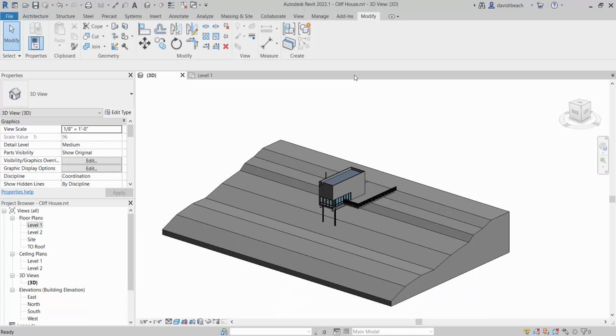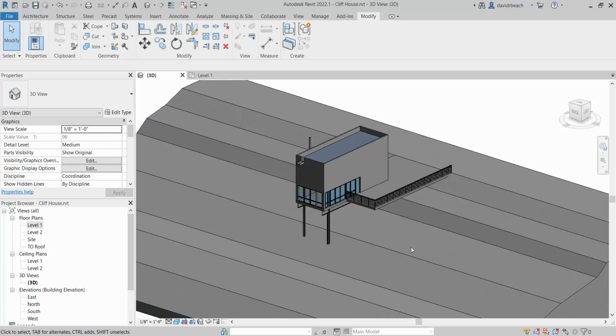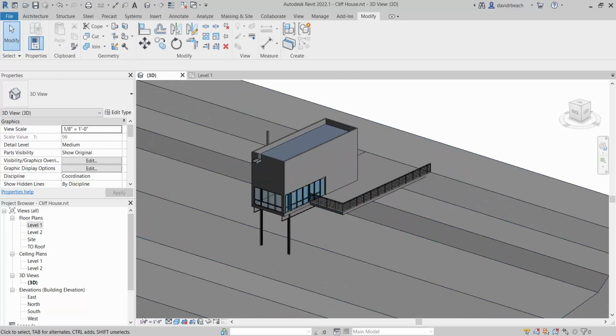Okay, so the thing to remember when you start putting together hidden line drawings, the first thing to remember: this default 3D view is an axonometric. It is not an immersive drawing. There are times that we need axonometrics. They do a good job showing us volume, but I know that this is an axonometric because it has a scale. Right now I'm working at 1/8 inch scale.